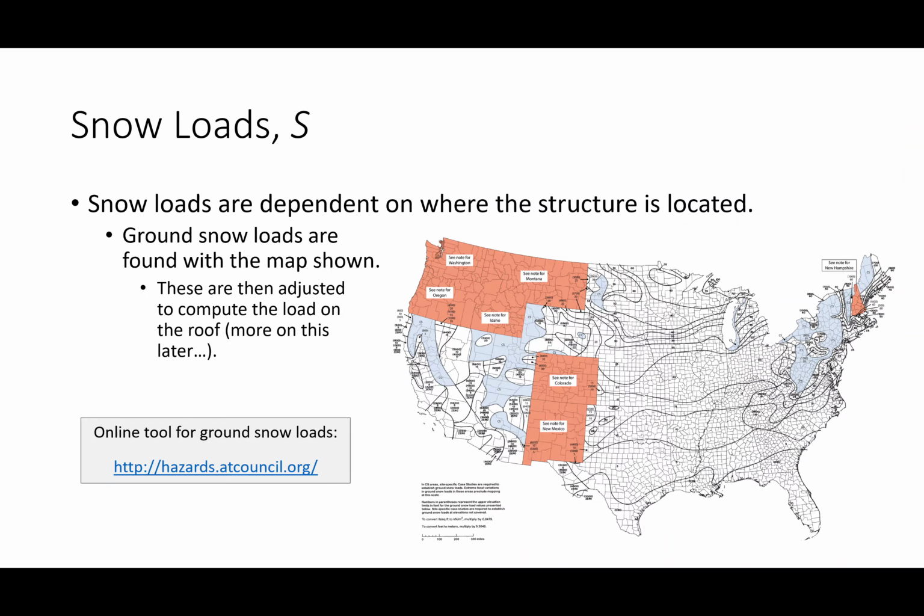Okay, snow loads. Snow loads are obviously a function of where you're at in the United States. For example, this is the snow load map for the United States. This is from an older edition of the spec, admittedly, but the patterns aren't really all that different. There is one state that has its own snow map by itself. Which state is that? Well, okay, so Colorado has some specific notes, but he's right too. Alaska's going to have its own snow map because it's Alaska, right?